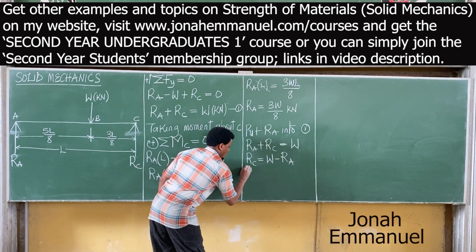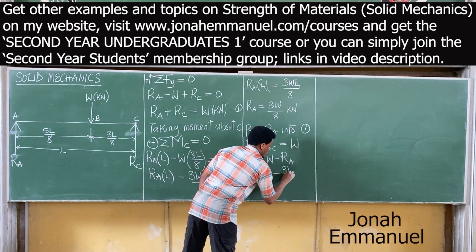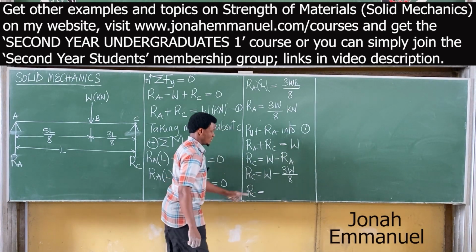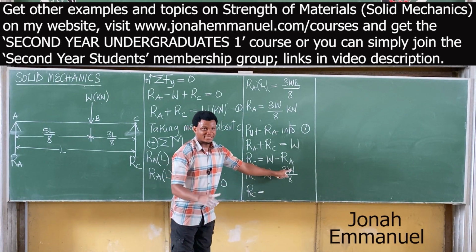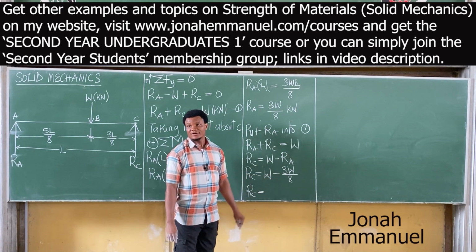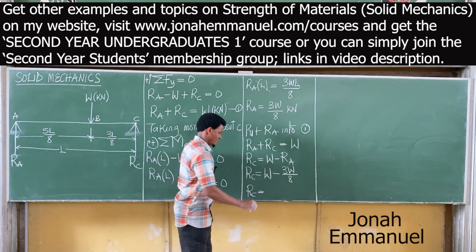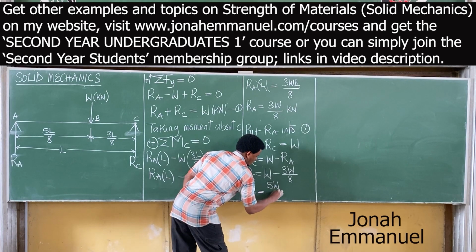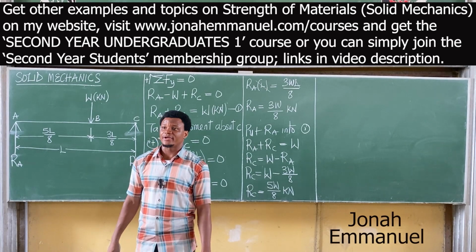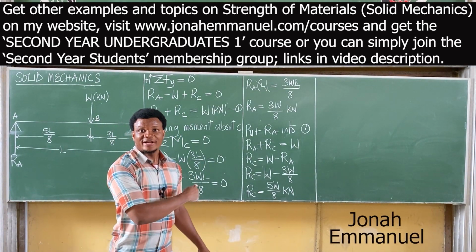All right. So RC is equal to W minus, what's RA? 3W over 8. So RC will now be equal to, I've said W and W, work with the numbers. I'll now have 1 minus 3 over 8. What do you have? 5 over 8. 5 over 8 times W gives you what there? 5W over 8. Of course, also in what there? Kilonewton. With this, I've got the value of RA as well as the value of what? RC.